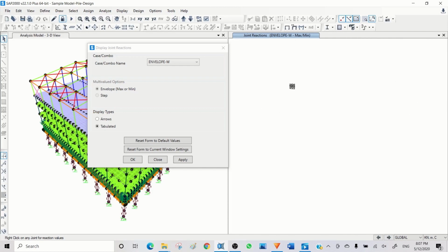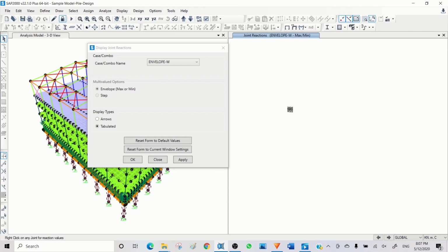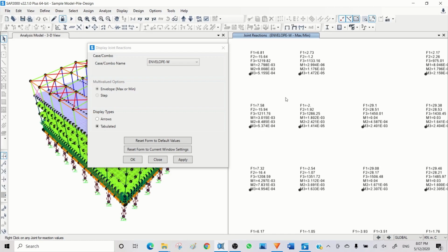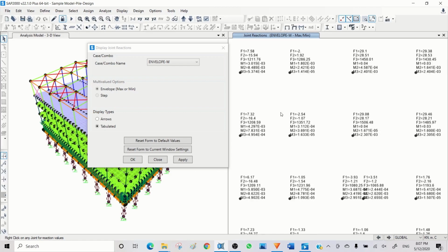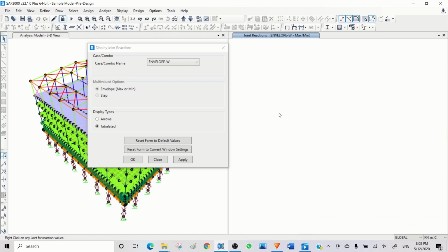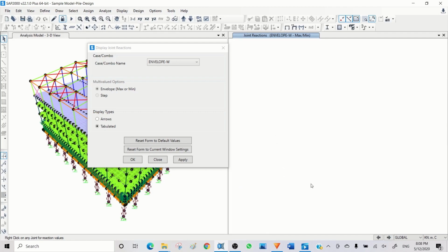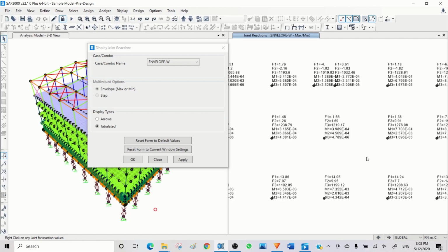So this is working stress. I need to see what is the end bearing capacity of the pile at that certain founding level where the pile is founded, and also what's the socket length and what's the skin friction of the pile, and the combination of these two gives me the capacity of the pile. So if the capacity of the pile is something around 1300 kilonewton, I would say these piles are okay.